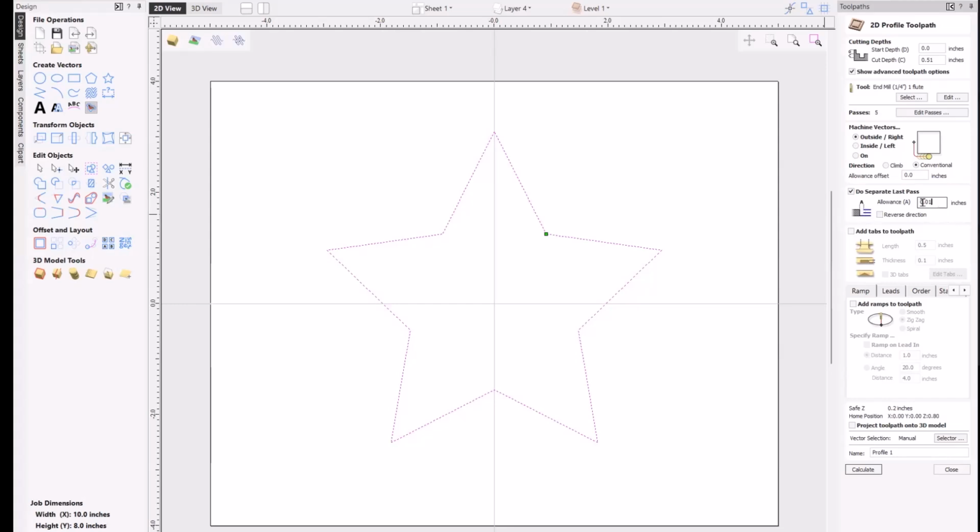Because when you cut in layers without this set up, you are likely to get some step marks on the edge of the board from the router bit. That's just the way it works. If you get excessive step marking, it could mean that your tool is not trammed correctly, which means it's not perpendicular to your table, which is a different problem. But this is a way to get a nice smooth edge on your project. You can even do a reverse cut if you want to.